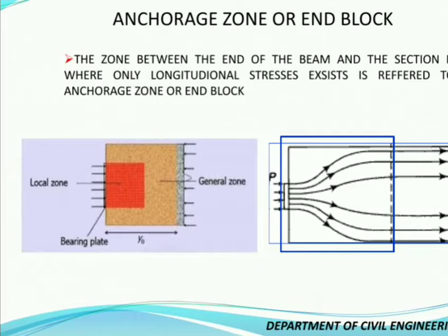If you are working on a site where post-tensioning is going to happen, as a civil engineer, it will be your duty to check this anchorage zone or the end block, because if adequate reinforcement is not provided in this block, it will lead to bursting action, which we will study, with the formulas and all the details, in the further lectures, and it will cause huge damage to the concrete in and around this region.